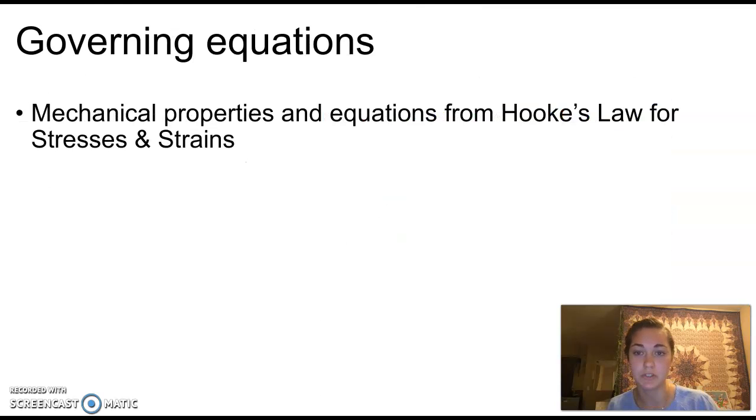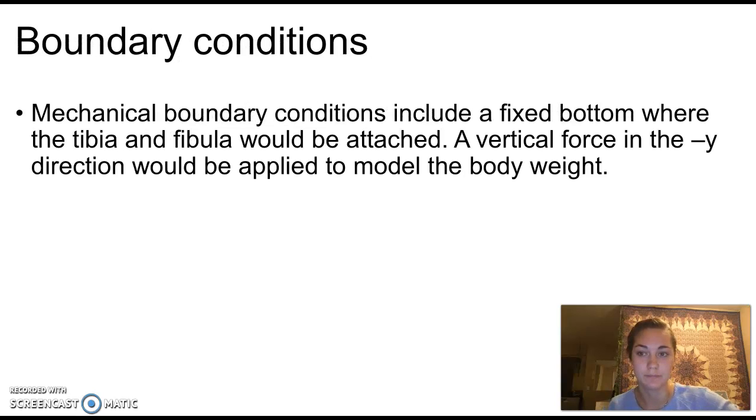The governing equations used. So the mechanical properties and equations are being used from Hooke's law for stresses and strains. Boundary conditions. So the mechanical boundary conditions include a fixed bottom, where we saw in the mesh slide, where the tibia and fibula would be attached, and a vertical force in the negative y direction would be applied to model the body weight on the knee implant.